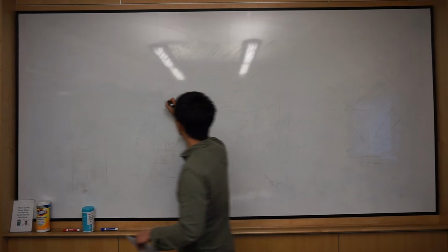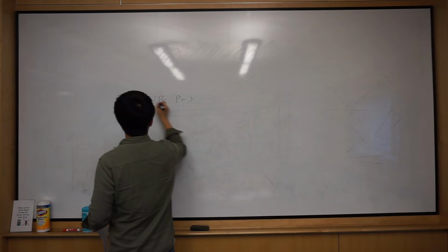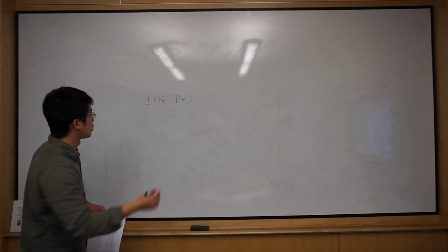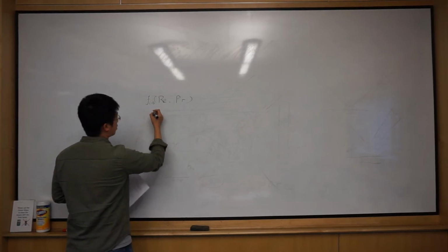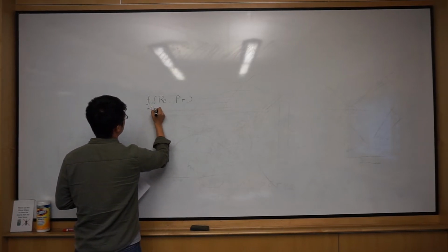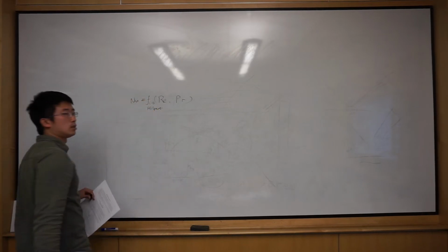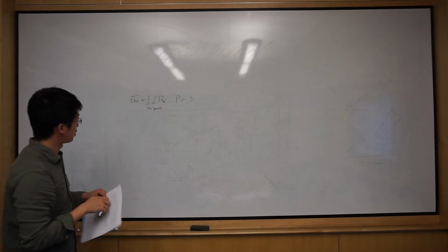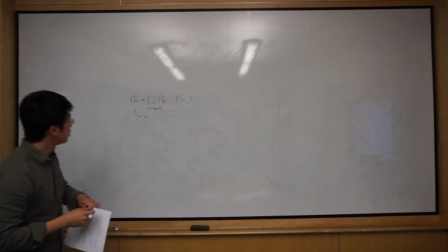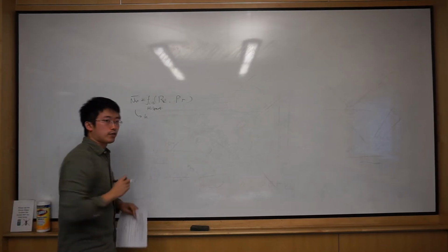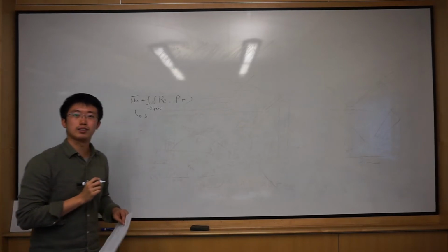So we start with the Reynolds number, and we also know the Prandtl number. In this one, we know one correlation. For example, you want to use the Churchill-Bernstein, whichever you want to use, you can get the Nusselt number. This is the average Nusselt number. And then from this one, we can get the heat transfer coefficient. And after this, we come back to the thermal resistor analysis.